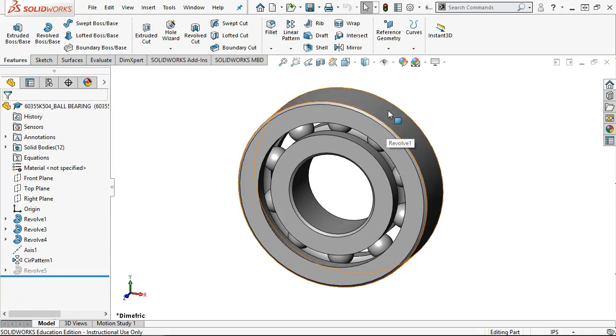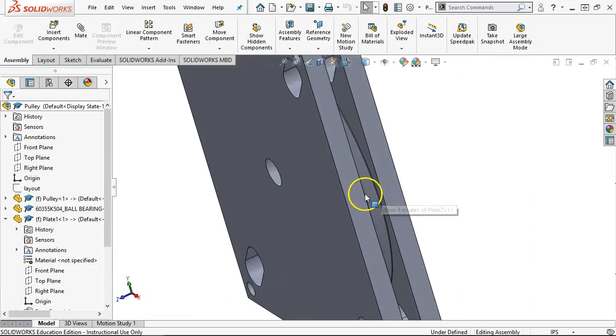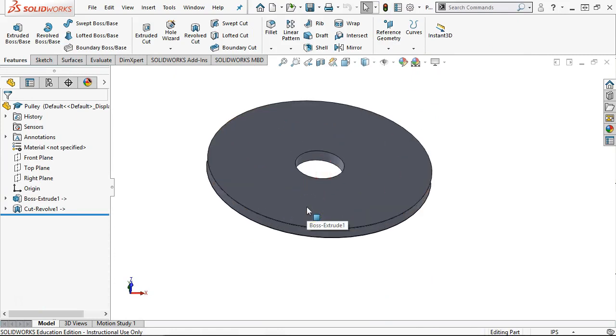It has its standard tolerances: plus nothing, minus five or six tenths of a thousandth, and we looked at those numbers. And then in that chart I was referring to, the FN1, which is a force fit, has a range. A light fit is from 0.2 of a thousandth to 1.1 thousandths, and a heavy fit is from about a thou to almost 2 thousandths, so 1.9 thousandths. I don't really want to start just throwing them out as 19 tenths of a thousandth.